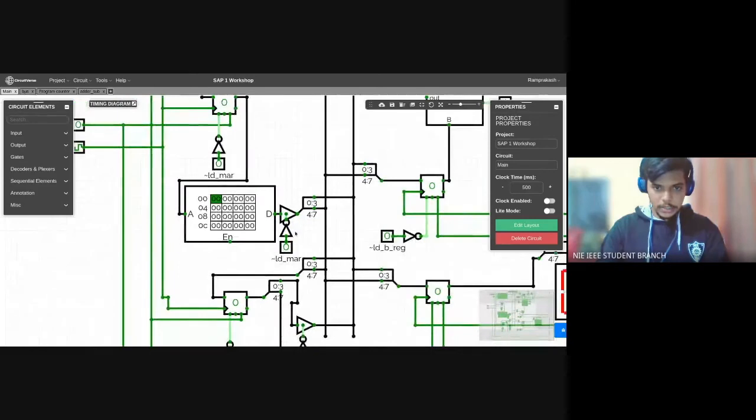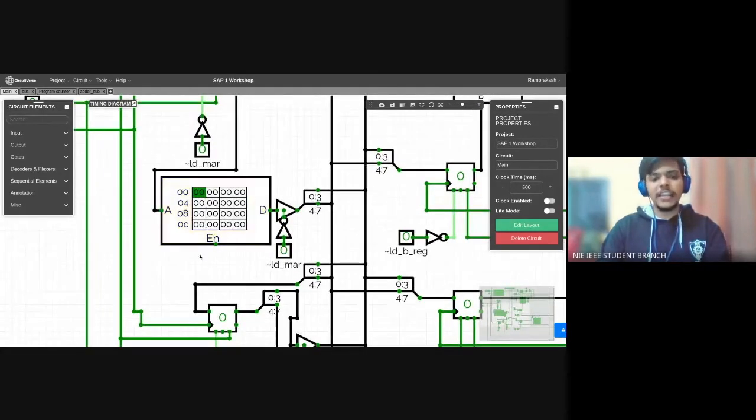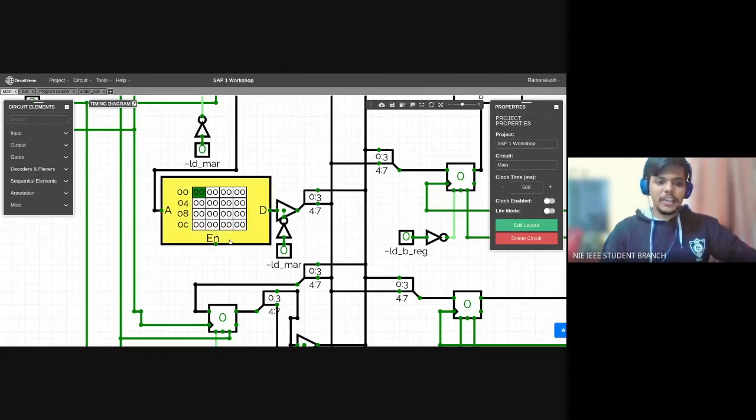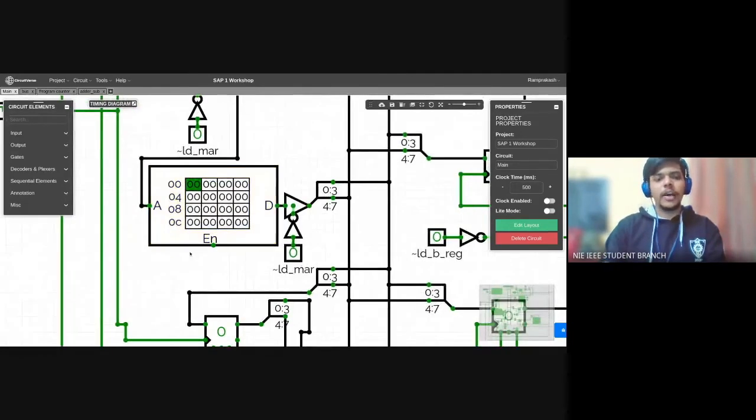Another thing, you see this EN here, so that's like the built-in output enable. That's not very convenient to use, but the way this inbuilt circuit works is if this is set to high, that's when you'll get the output here. Otherwise it's going to be like an unknown state. So I'd rather just put this as 1 fixed.